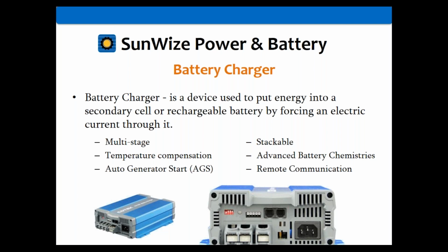Okay, but again, the key here is the battery charger is not designed necessarily for the voltage, but it's designed to recharge the battery by putting current through it. If you remember some of the webinars, I talk a lot about how it's important to get the amps into the batteries. That's why batteries are rated in amp hours, and how important the amps are. It kind of comes back to this again. In this case, the battery charger is about the amps, whereas a power supply is more about the voltage to the load. The other thing is the battery charger is going to have other things in it that are good for trying to charge your battery, whether it be multi-stage.